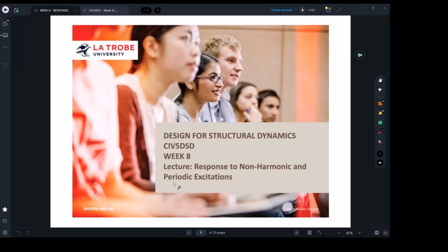Then last week we talked about pulses, just one single pulse, something like this, and we talked about the shapes and the forms. So that's what we've done so far. We're still talking about single degree of freedom systems, but what we talked about so far is synthetic motions inputted into the equation. Synthetic motions are simplified motions like the harmonic sine function and cosine function. And last week we talked about the single pulse motion, in which we covered three shapes: triangular, half a sine pulse, and rectangle, right?